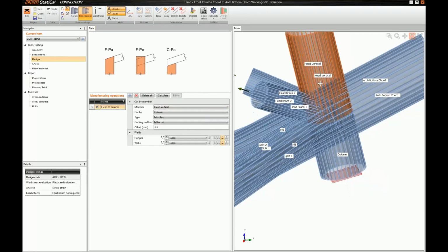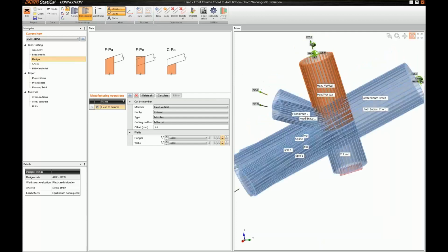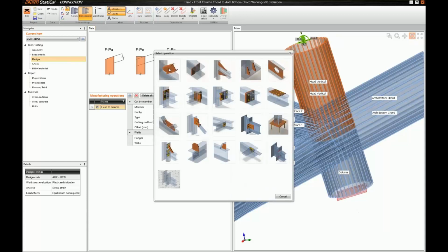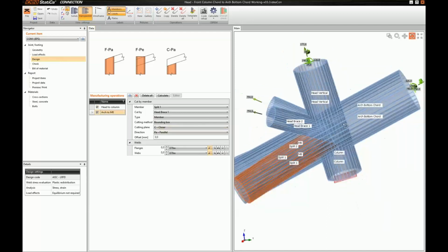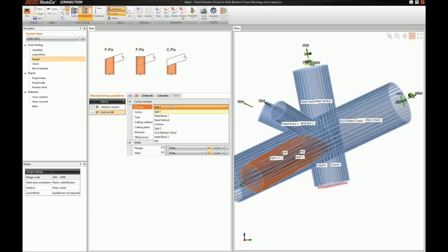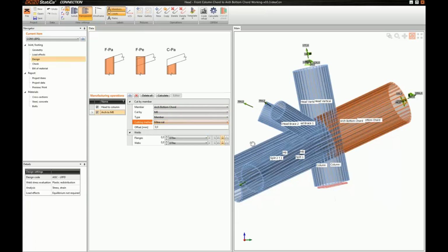And then, after I have welded these two elements, I will weld the arch bottom chord. Again, I will use a miter cut. I will rename this to arch to M8, so that I can connect this horizontal member here. Again, I will use the arch bottom chord and the M8 member and use a miter cut.